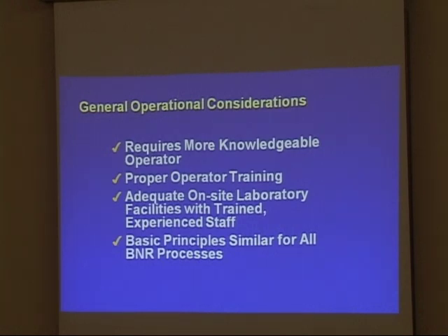We've been through a lot of training classes and laboratory facilities, and the basic principles are similar for all the ENR processes, as you're starting to see, whether you're nitrifying, denitrifying, or doing phosphorus removal. This is how you set up the stage based on your tank configuration, and then you have your specific SRT and other process adjustments like the IR and controlling side streams.